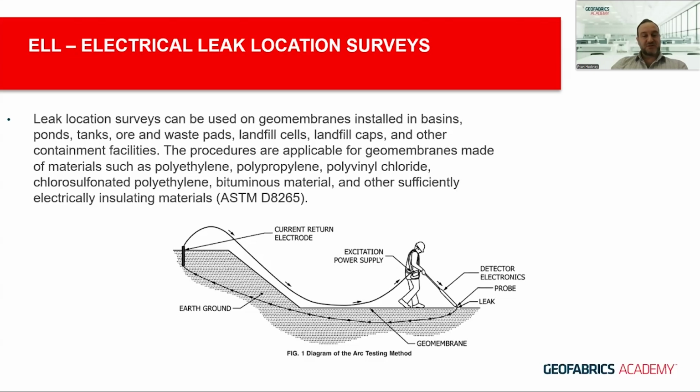The procedures for conducting these leak location surveys are applicable for geomembranes that are made of a variety of polymers, and that would include polyethylenes, polypropylenes, PVCs, CSPEs, but also bituminous type membranes as well. Basically, any type of material that's sufficiently electrically insulating, and that's a brief description taken from ASTM there.